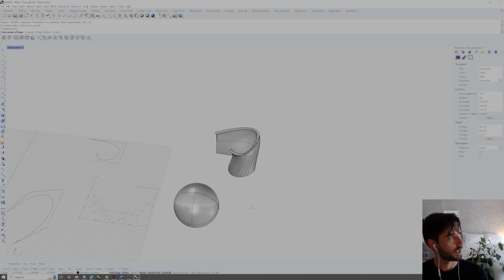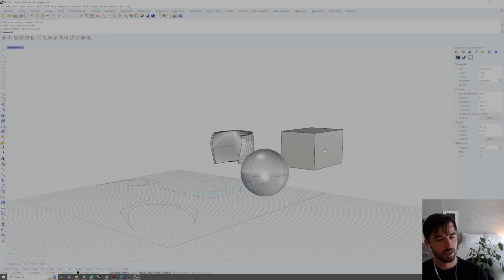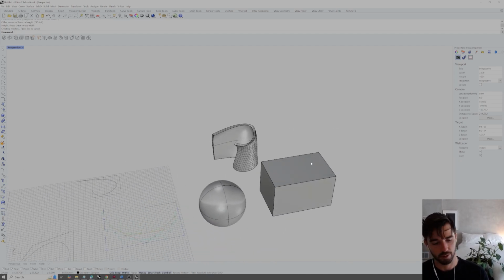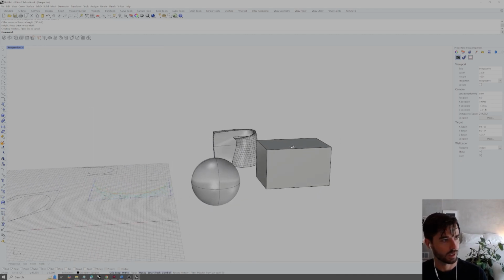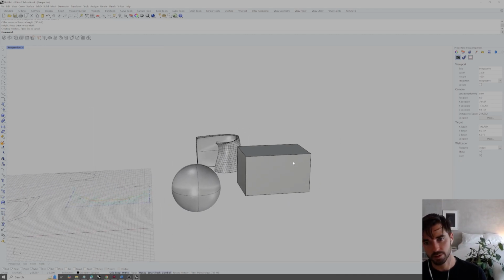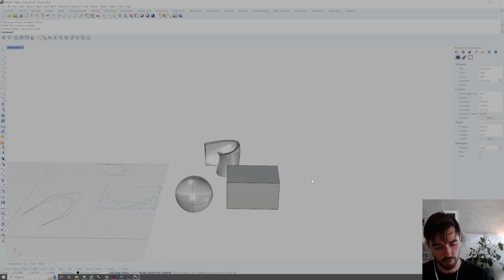We can do the same thing with box. Draw a box, it's asking for width and then height. So we can define that by a rectangle at the base, 2 points at the base, and then click again for the height definition, or we could have typed in numbers to define that. We can also do things like cone, click to set the base, 10 for a radius of our cone, 20 for the endpoint.